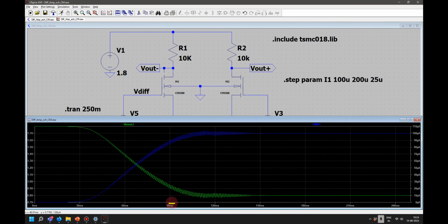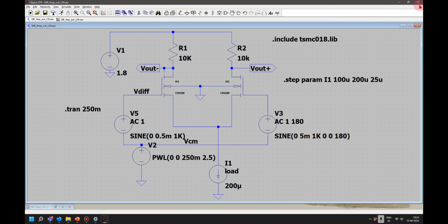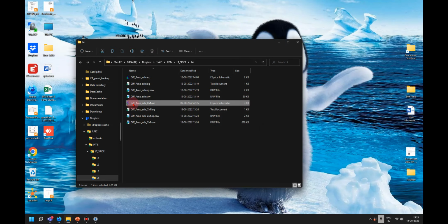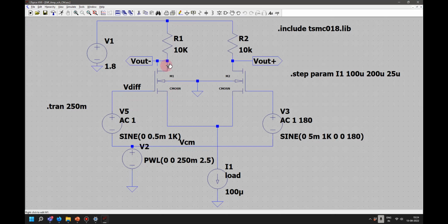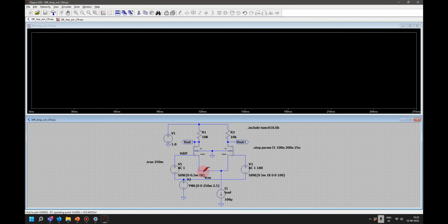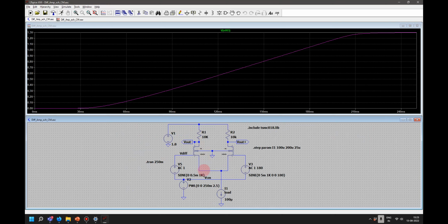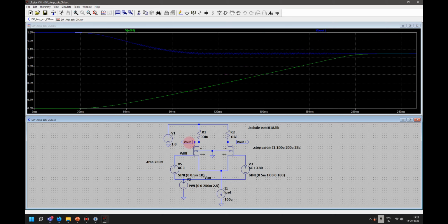And sir, in this simulation, if you plot the voltage at the source of the MOSFETs, that will also saturate. Basically it is not increasing more than 1.3 volts. Yeah, because you have IR drop, right? So 1.8 minus 50 into 10 kilo ohms. That will limit it to 1.3 volt, and then even if we keep on increasing the gate voltage, VGS will drop below VT. Correct. And then it will come into triode. Okay, sir. So these kinds of simulations you can do.